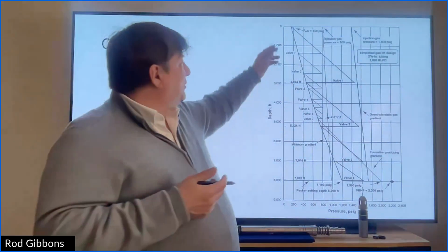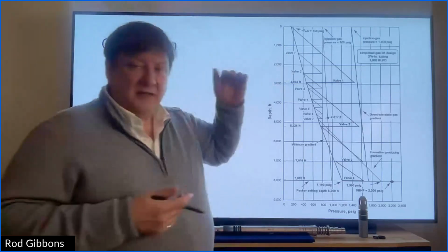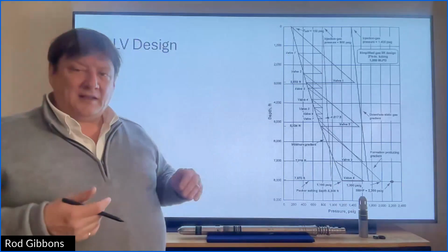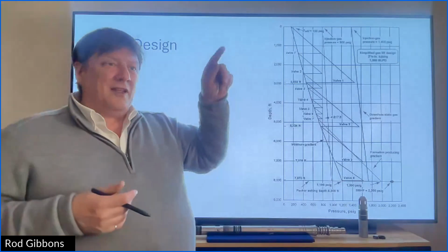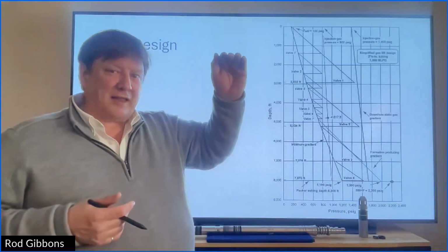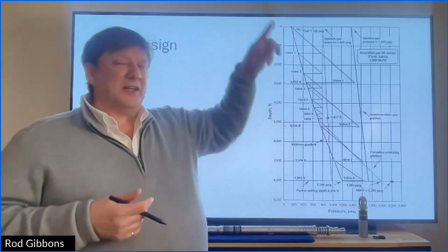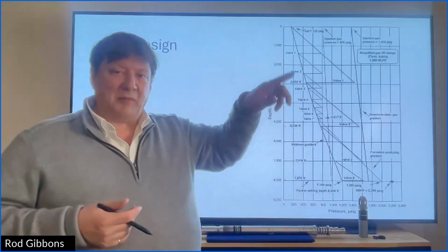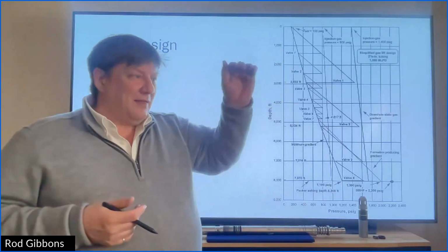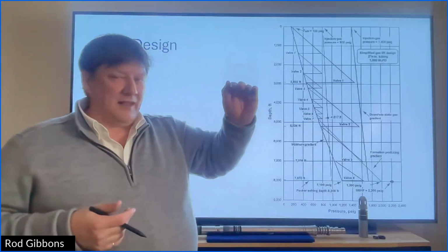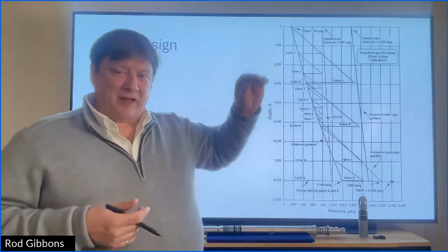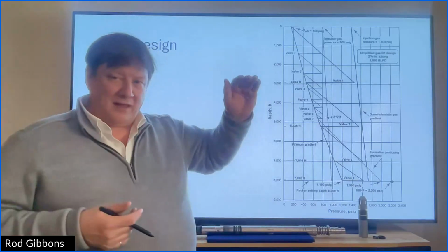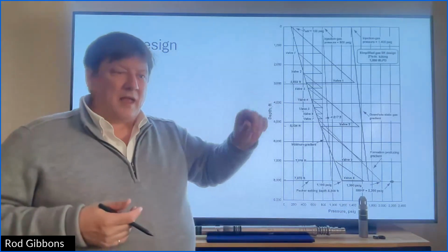So what you will do is add valves in the tubing string so that you only need to get the gas down to that first valve, and then it starts unloading. Then it starts bubbling. Then that valve closes and the gas moves down to the next unloading valve, and that starts bubbling, and so on, all the way down.